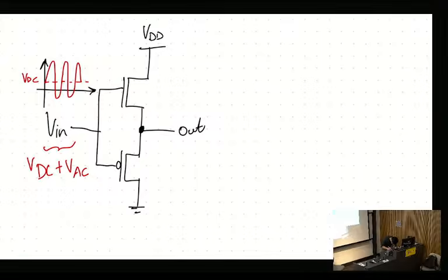So in this case, when the signal is high, in this region here, this NMOS is on, and that means we're pulling this way. In the case where it's negative, the PMOS turns on, and we go this way. You'll notice we have standard AC operation. When the signal is high, it's pulling from VDD, and current is flowing in this direction. But when the input is low, we are reversing polarity and pulling to ground. That's why we use this sort of totem pole configuration for our power amplifiers.